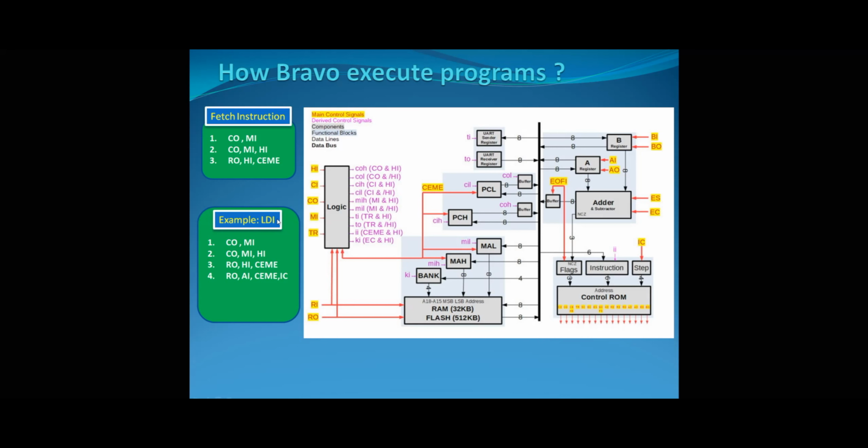Assuming that we already have that value set in the next memory address, what is happening here is just a RAM out and A in. So RAM out puts the content of that memory address, which has the value that we want to put in the A register, on the bus. And A in basically just reads that value from the bus and puts it into a register.